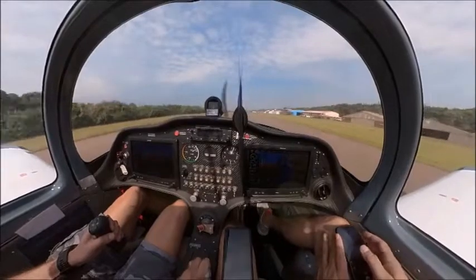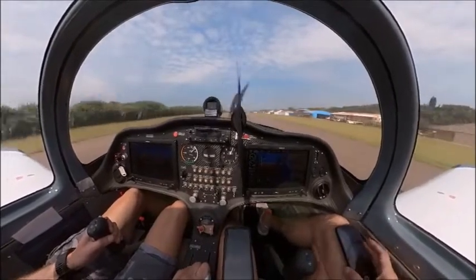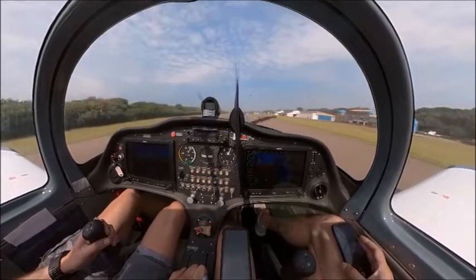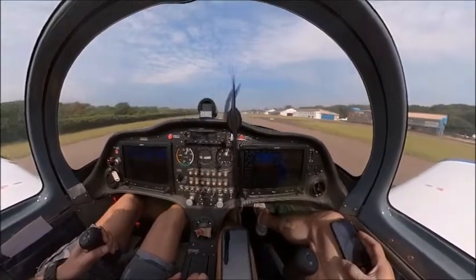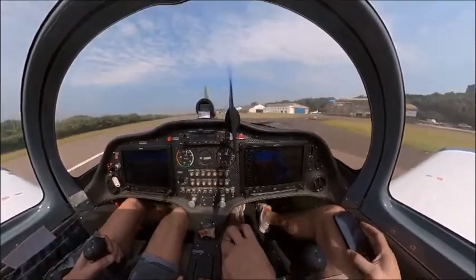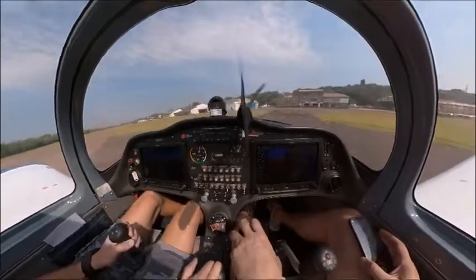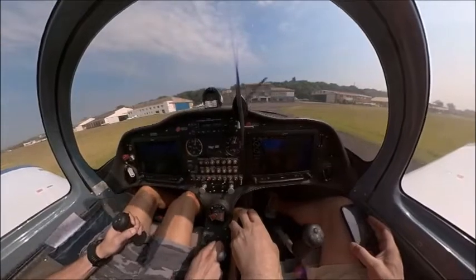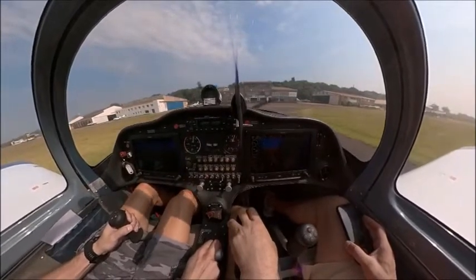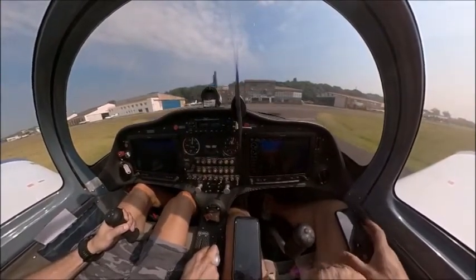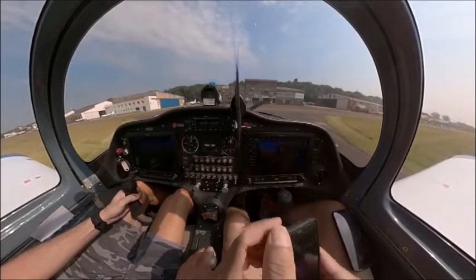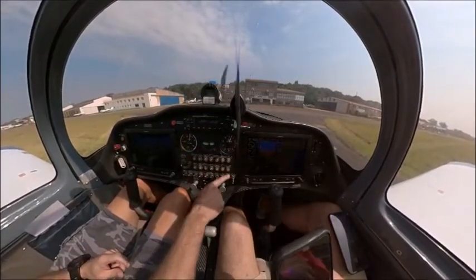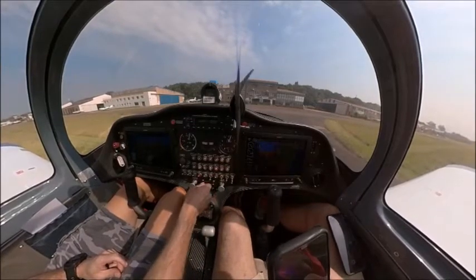As we get to the end of the flight, we have to reset our configurations in the aircraft. Then we have to follow different instructions in terms of completely switching off the different instrumentation, the avionics, and the engine, to make sure that everything is done in a certain procedure, because we can blow certain instruments. For example, if we switch off the engine before switching off the avionics, the avionics can be damaged.